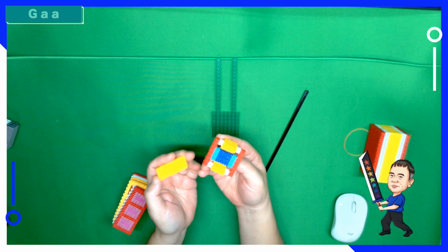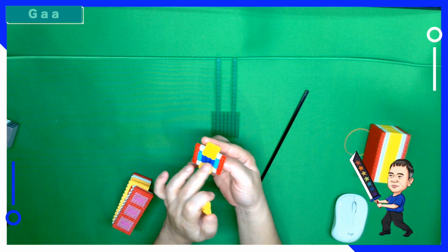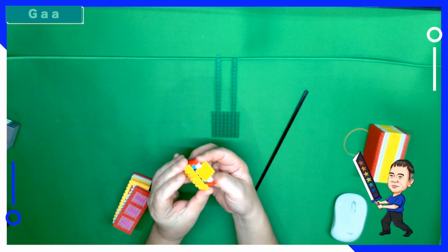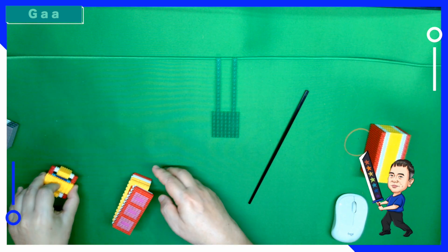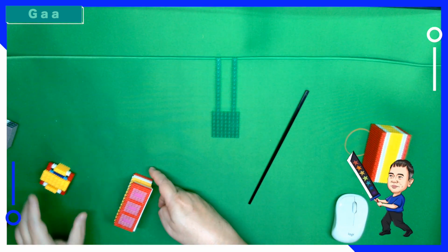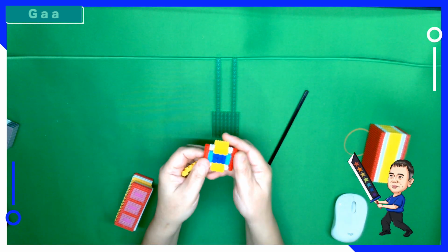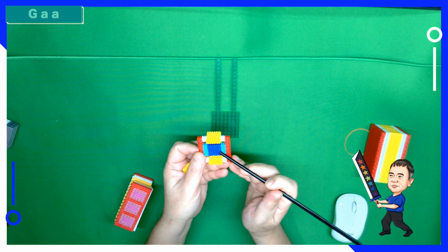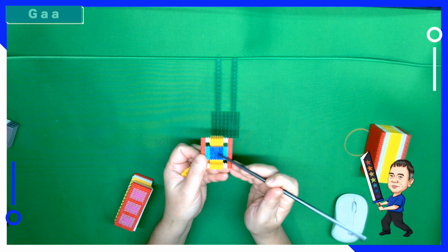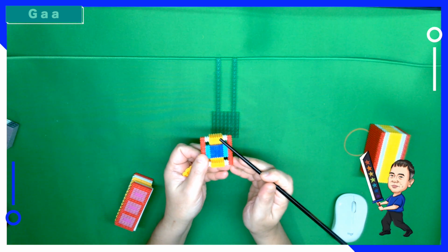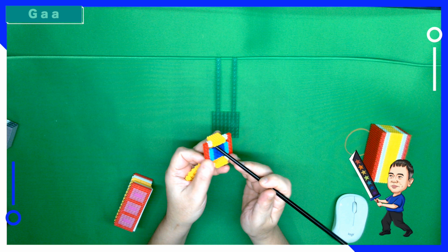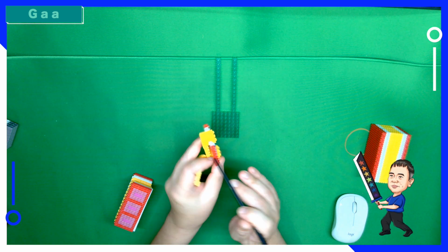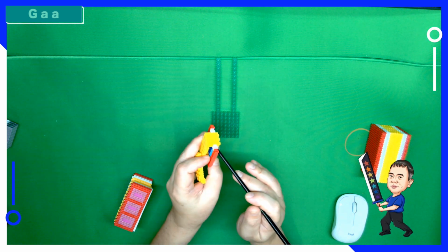Okay, now this is one bridge or one sheet. Sometimes one bridge is not enough. Why? Because to have the gate-all-around effect, the size of the bridge cannot be very large. The effect of the gate must be able to affect the whole channel, the whole plate, the whole sheet.